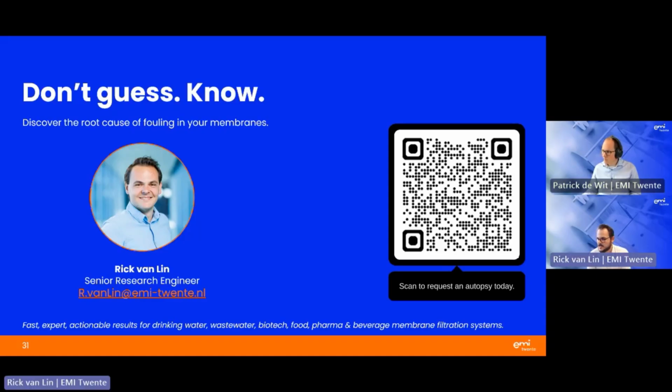Yeah. I wish I could say, yes, here's your answer, but at least to my knowledge, the antiscalant is pretty much all you can do, except for accepting a loss in recovery. So if you concentrate less, you'll get less scaling, and other than that, it's just the antiscalant, unless you want to go all the way up to membrane modification, but that's a whole different topic.